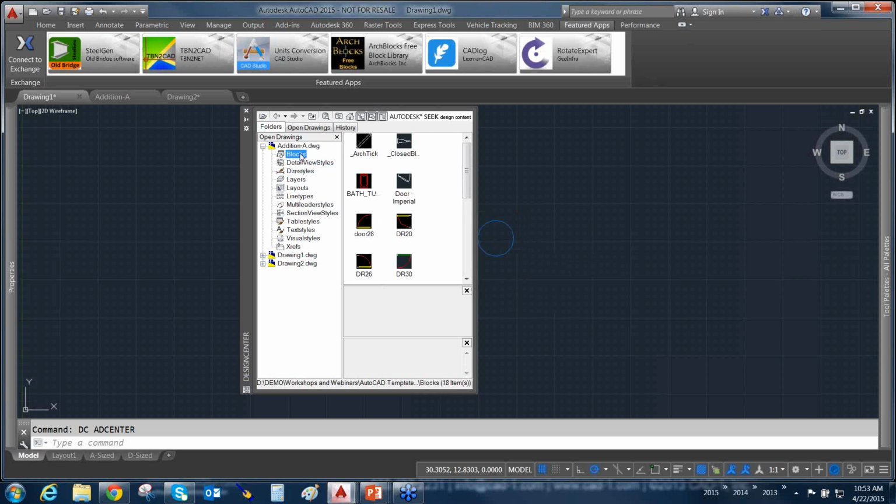Now, why couldn't I just copy and paste the block out of one drawing into another? If I use the Design Center, what the program does is it will literally recreate that object inside my drawing. So it will not insert it, thus bringing in all the reg apps and the errors. Best to use Design Center. So James, hope that helps you.